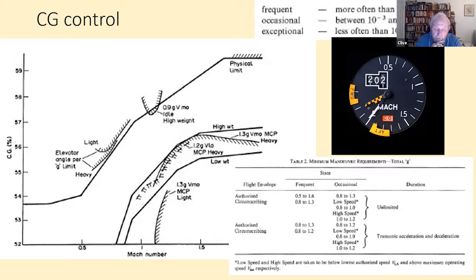But they could be fed in an emergency by the standby yellow system, which could be fed to either side of the jack. So in order to get to a half hinge moment situation, you actually had to have 2 hydraulic systems out of the 3 failing, but you could still just get that inside 10 to the minus 7 per flight. So what we ended up with, the limits that we found ourselves in the end, again, you may remember this is on a single hydraulic jack.